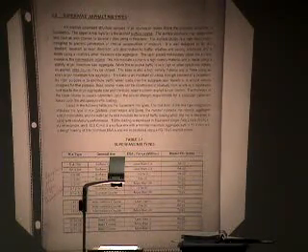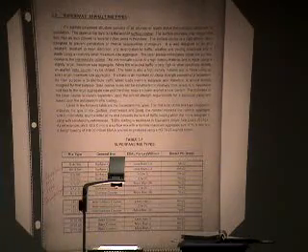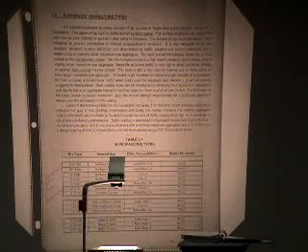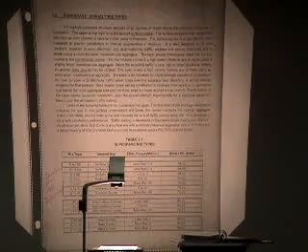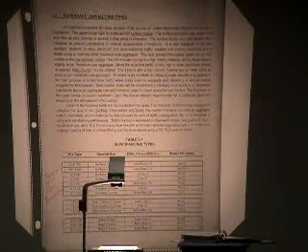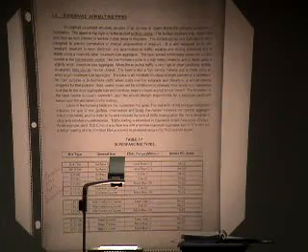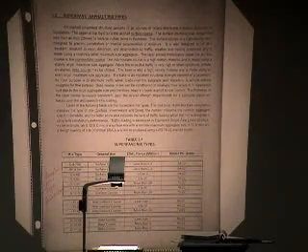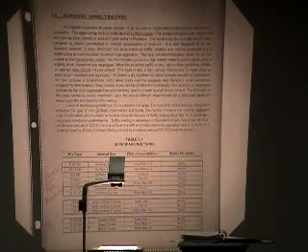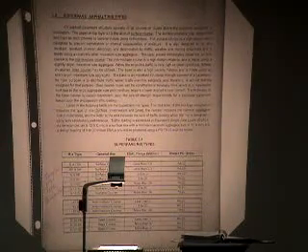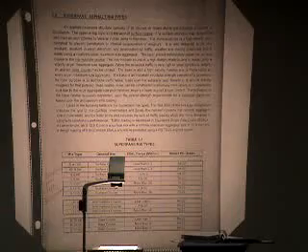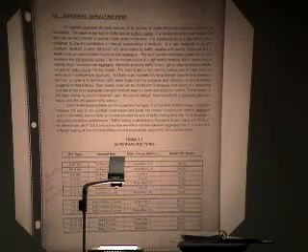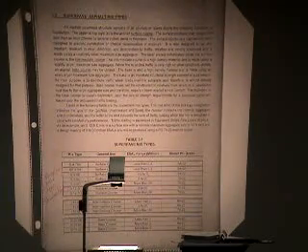Now in the western part of the country, we had several years of real hot weather where it stayed hot day after day after day, and those pavements got real hot, real deep, and just stayed that way. It didn't cool off significantly at night, and so that contributed to rutting. At about the same time, tire manufacturers were modifying the way they made tires, going from a design pressure on 18-wheeler tires of 100 psi to 140 and 150 psi. That concentrated the load into a smaller area, and that increased the stress that caused additional rutting.